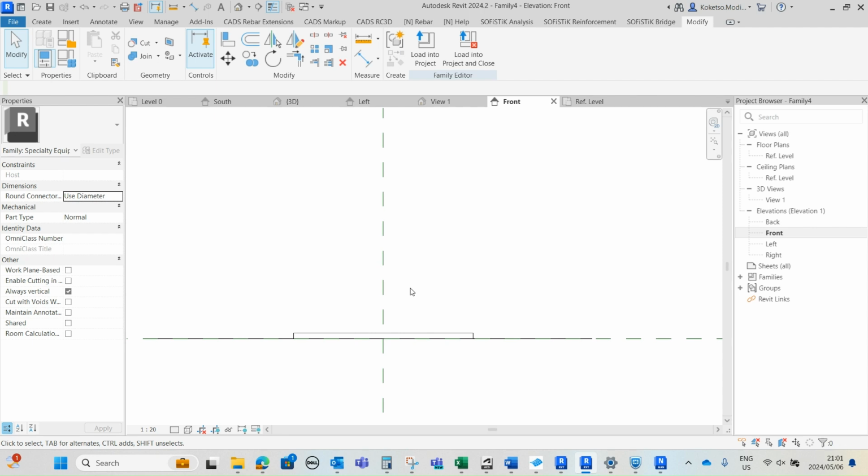The steel plates, there are going to be four of them and they're going to be embedded within the rubber, within the elastomer, and they are going to be 5 millimeters in thickness. The inner layers, which are the rubbers, there are going to be three of them and they're going to be 10 millimeters in thickness. And then the side covers, there are going to be two of them which are running across the perimeter of the elastomer. So they're also going to be 10 millimeters in thickness.